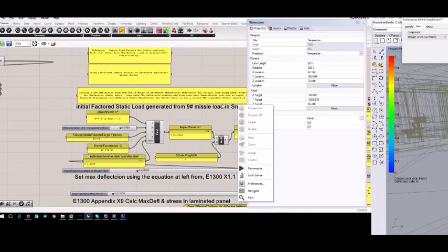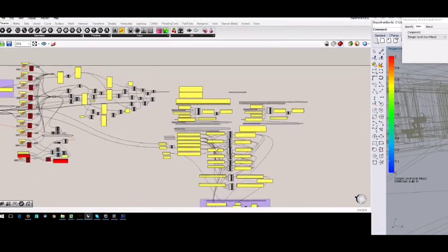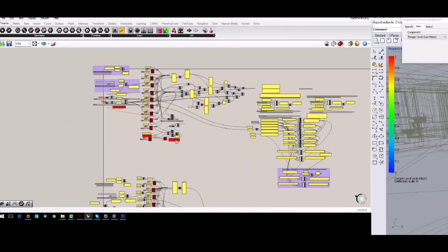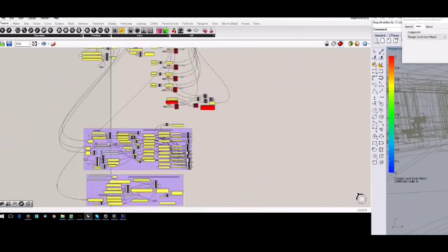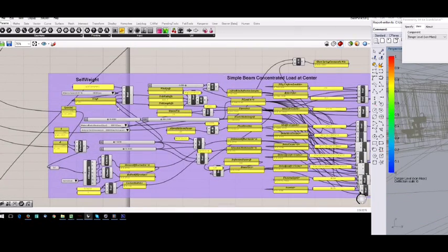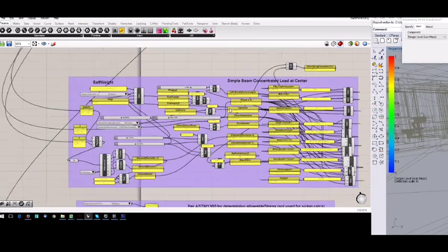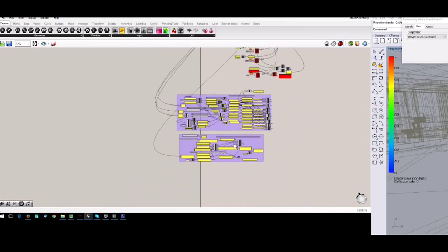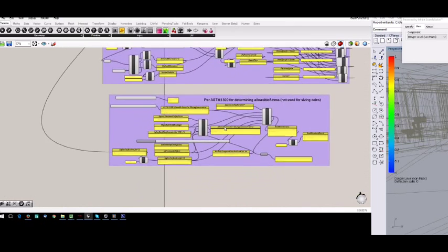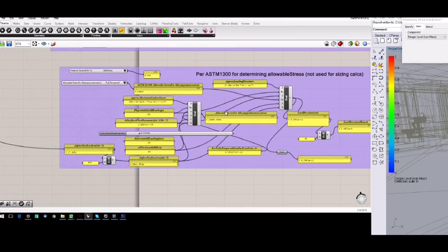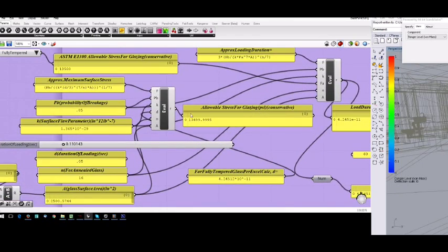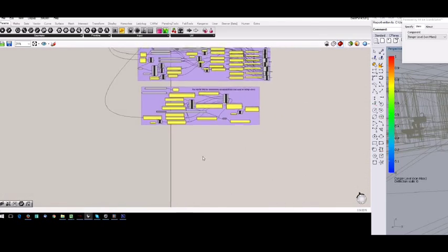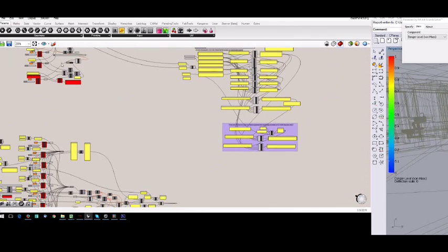So you see, we break it down into just the very basic elemental pieces. We just need to know how to find the loading on it, dead load, live load, wind load, and then we just need to know how to size a member, whether it's wood, steel, glass, concrete, plastic, whatever it is, determine a size for the piece of material that we're going to use to support the load.